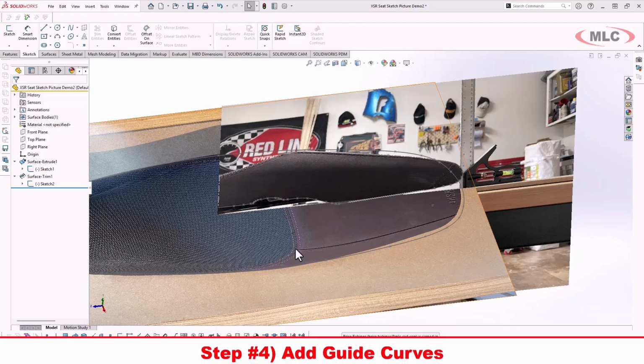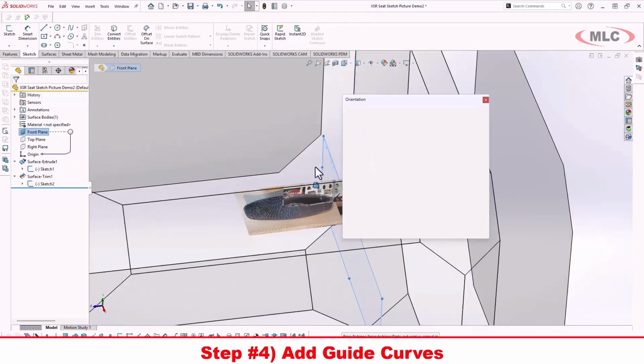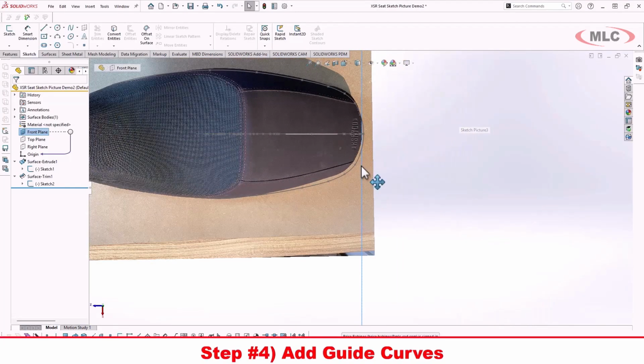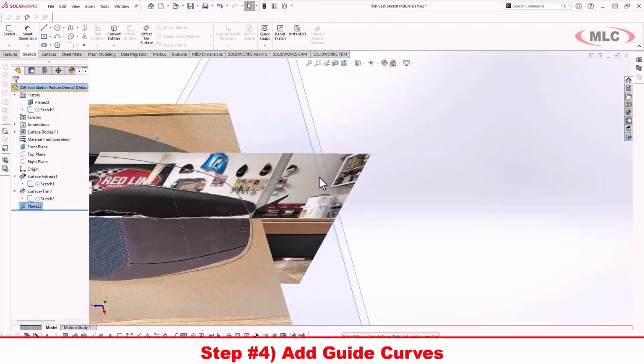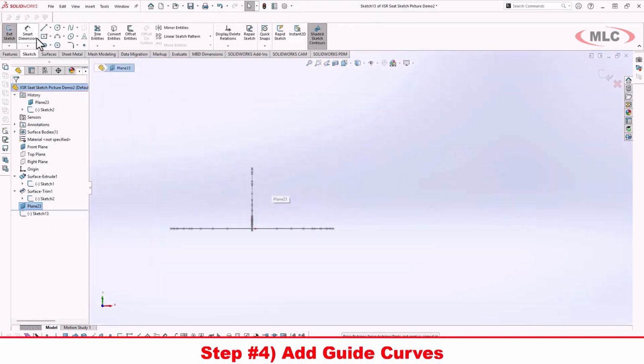So I decided to use those fabric seams again and break the curve up into two separate surfaces along that one main seam. And I'll use guide curves at the front where those seams intersect and one at the back where the seams intersect. So by holding Control and then clicking the front plane, I can kind of drag it out and create a new plane at that position where the first seam is at the back.